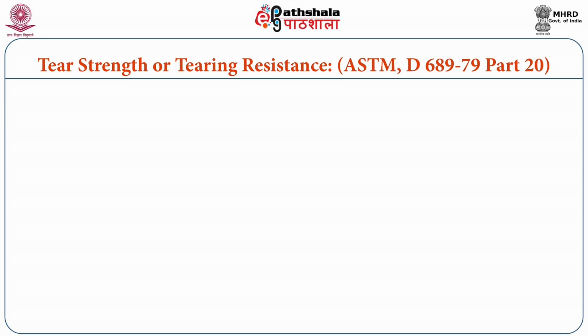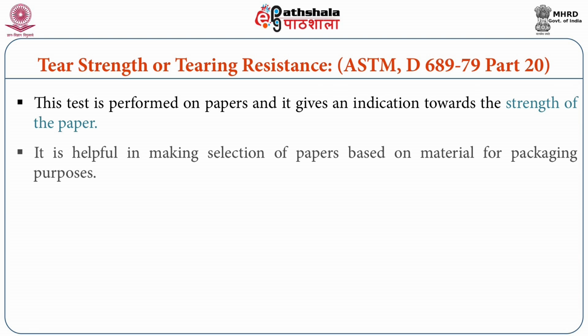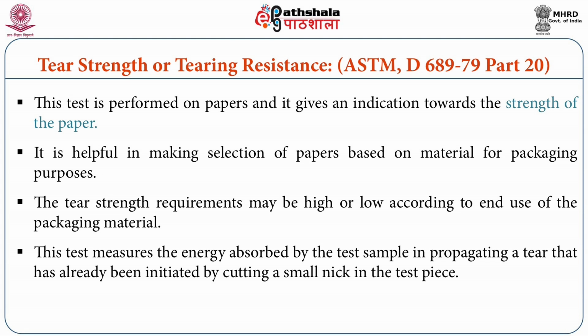Tear strength or tearing resistance is performed on papers and it gives an indication towards the strength of the paper. It is helpful in selecting papers based on material for packaging purposes. The tear strength requirements may be high or low according to the end use of packaging material. This test measures the energy absorbed by the test sample in propagating a tear that has already been initiated by cutting a small nick in the test piece.